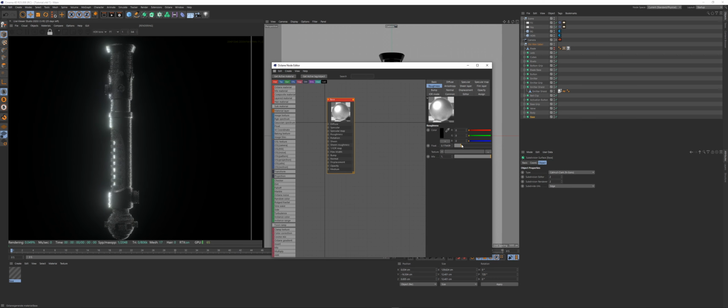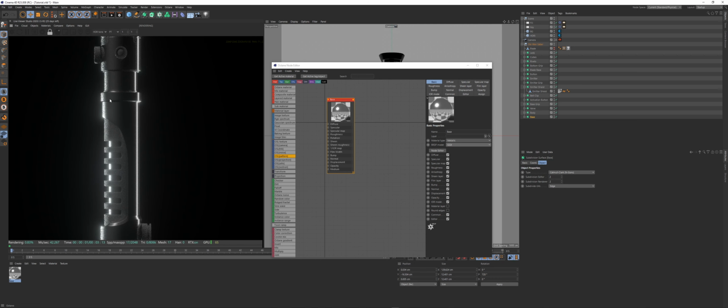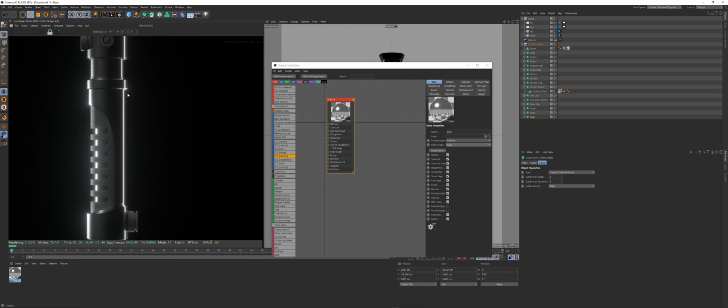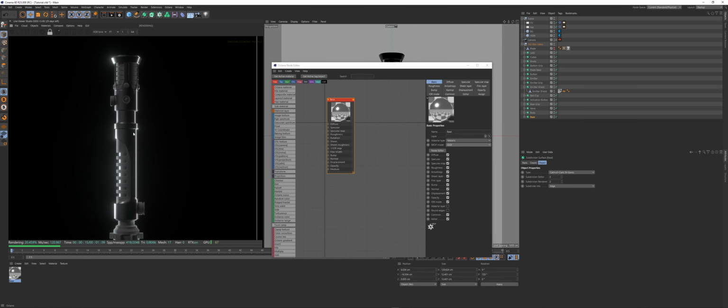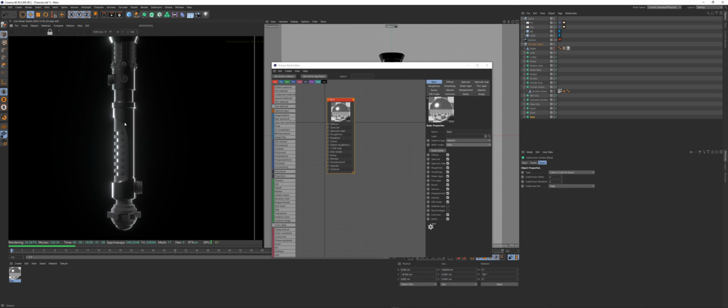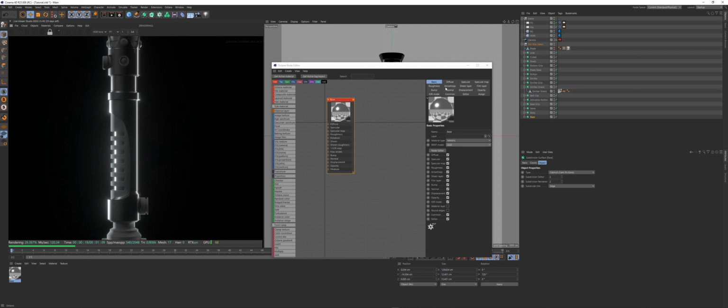You can just put your roughness up a little bit, but I would switch your BRDF model to GGX to immediately get these nice straight lines, as you'll notice on the renders I did, if you saw the one I put on my Instagram. You can get an HDRI to do that on the normal model or the others, but GGX is just going to hand that to you on a nice little plate. So I'm going to rock with that.